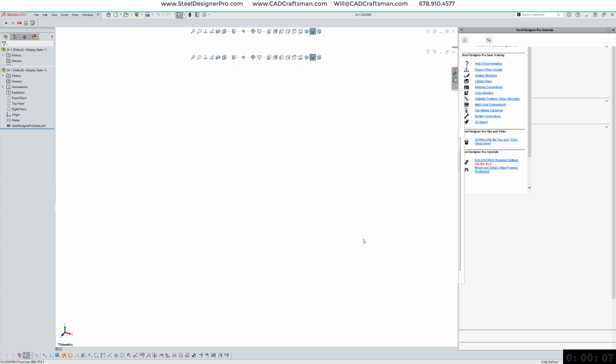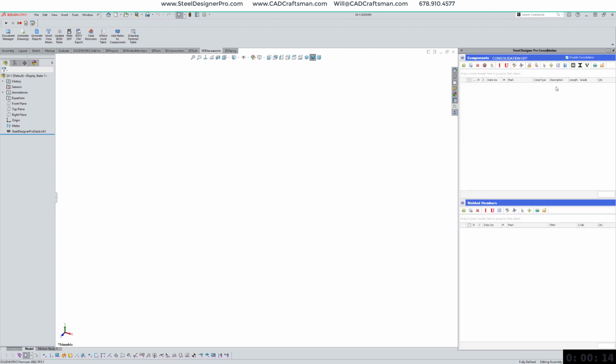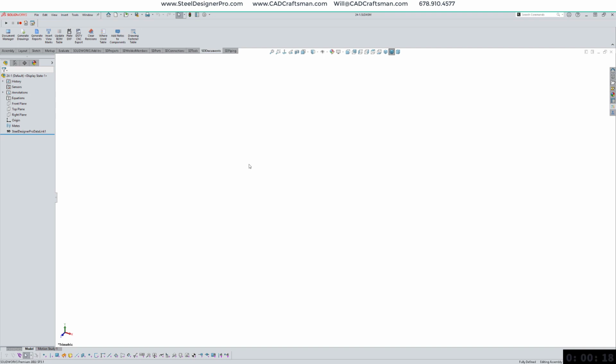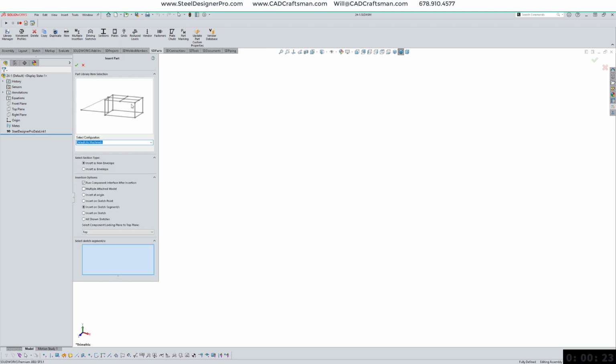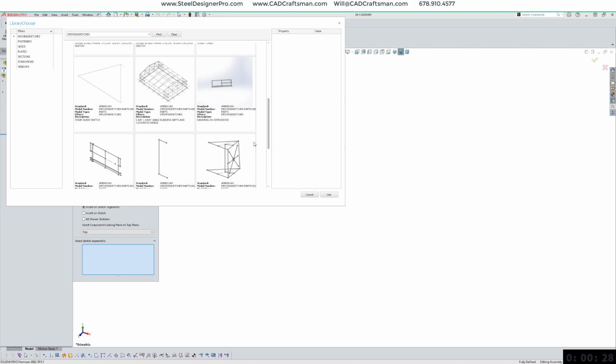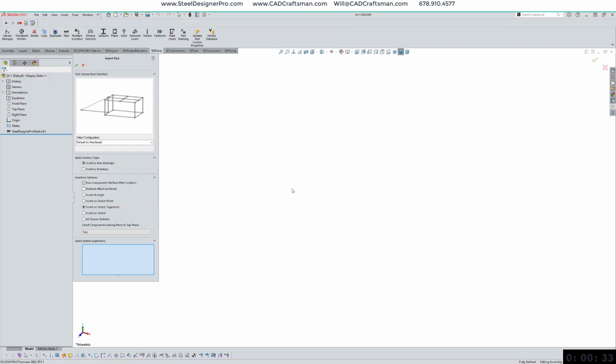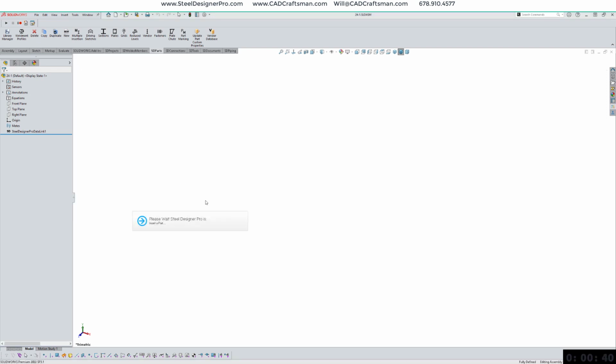While populating the model, it is best to check the box for Disable Consolidation to pause the process until we are ready. I will select the SD Parts tab and then the Driving Sketches button. This brings up the interface which allows you to access the library. Clicking on the image directs you to the library. Select the preferred driving sketch part and the Use button. Check Insert as Envelope and Insert at Origin, then the green check to start the insertion process.